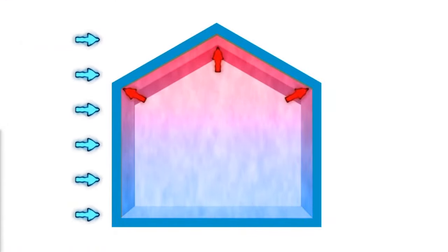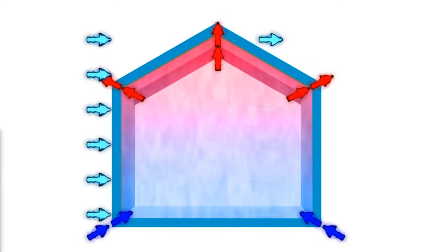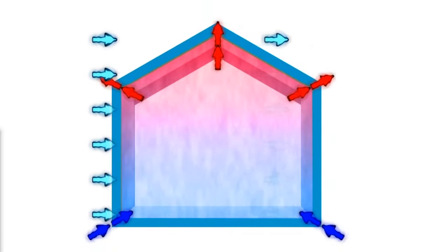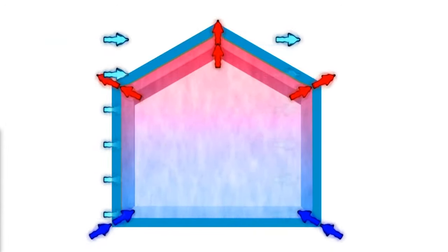Both the wind blowing and heat rising by convection internally can drive air movement, and this can dramatically impact the overall heat loss, especially as levels of insulation increase. Reducing this air movement is simple on paper, but can prove difficult in practice. Traditionally, air barrier membranes have been installed internally on the warm side of the insulation. Typically, these also function as vapour control layers to limit the ingress of moisture.